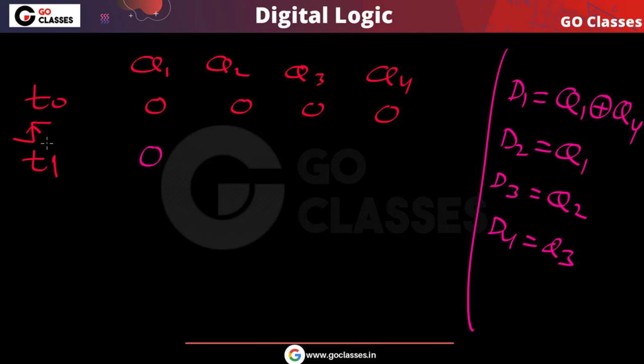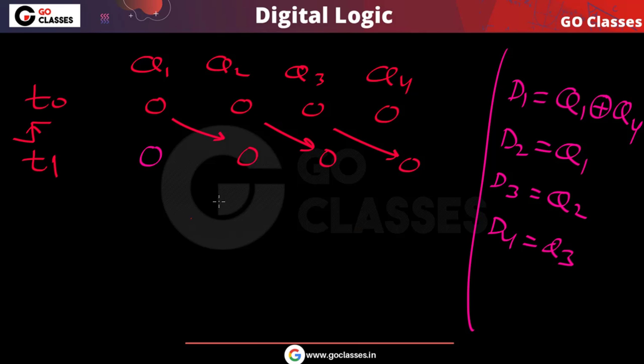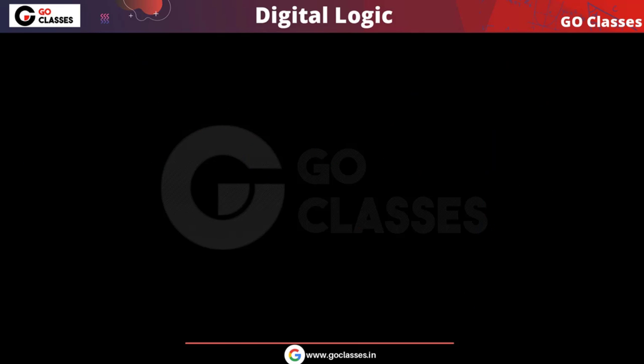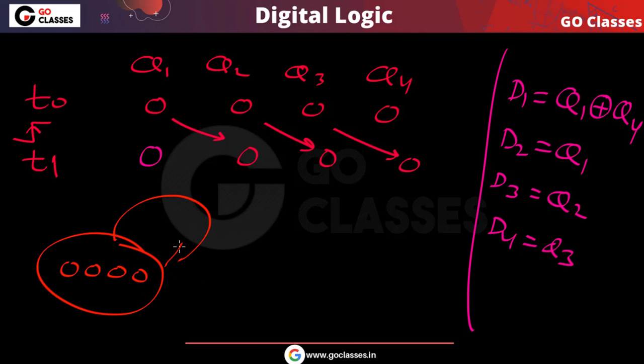So after one positive edge, what will happen? 0 exclusive or 0, that is 0. And then very simple: this 0 will go here, this 0 will go here, this 0 will go here. Now if you initialize this circuit with 0 0 0 0, then you will go to this same state again. You will never get out of this state.